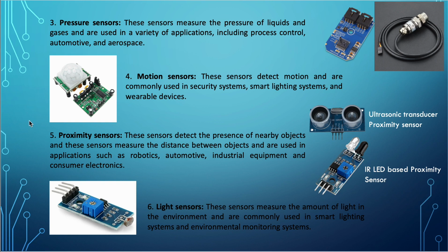So again, motion sensors. Seeing a problem and applying motion sensors, again like the examples above, right? You have to check the compatibility, the amount of power that is being used, and of course the effective distance. That is the main property that you must check.